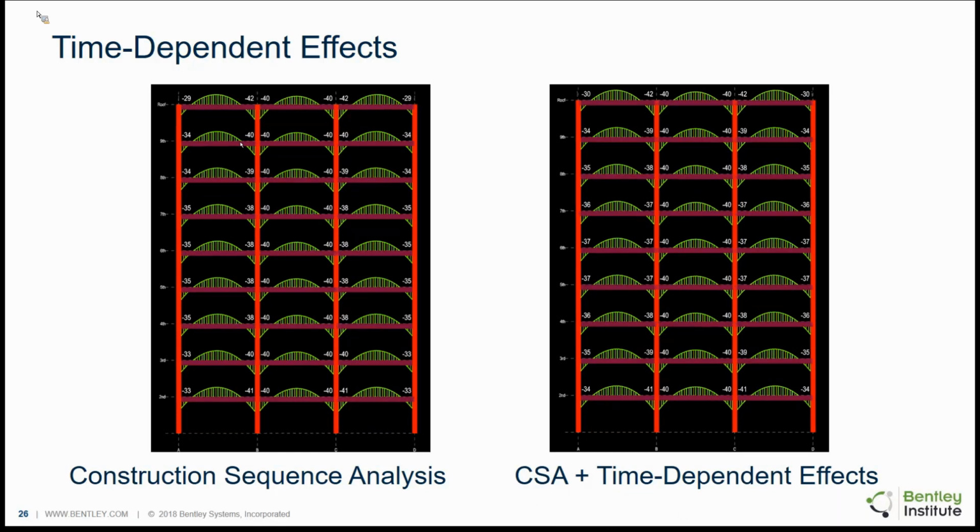And so looking at very long periods of time, what you would see in the analysis a month from now versus what you'd see 10 years from now wouldn't change very much, because the changes in creep and shrinkage are very quick in the initial stages of the concrete, and then they plateau out as time goes on. But in answer to that question, yes, the longer period would have more of an impact, but probably not significantly more.